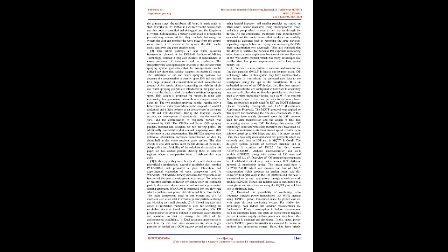3. In this paper they have briefly discussed an air microfluidic miniaturized wearable respirable dust monitor, WEARDM, and presented the design, fabrication, and experimental evaluation of each component used in WEARDM. WEARDM directly measures the respirable mass fraction of the dust in underground coal mines. To maintain uniform collection efficiency over the respirable particle distribution, the device uses a dual resonator gravimetric sensing approach. WEARDM is optimized for low flow rate, which equalizes low power utilization and small form factor.